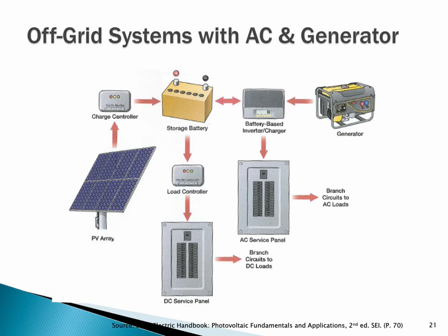So in an off-grid system, that inverter is going to operate independent of the utility, because there is no utility, and operate off a low voltage battery pack. But then it also has to be able to charge. So this is an inverter charger.